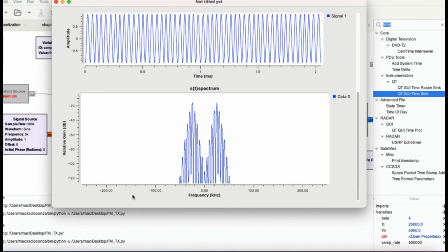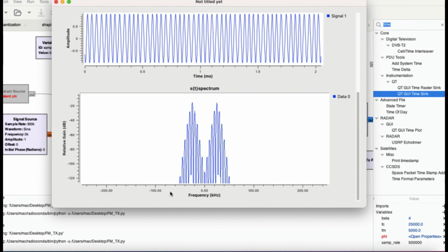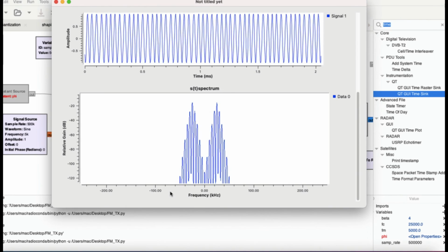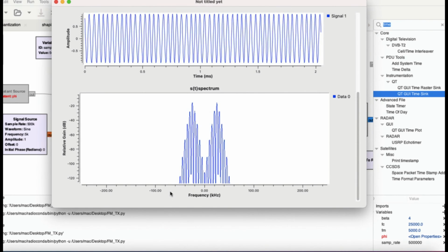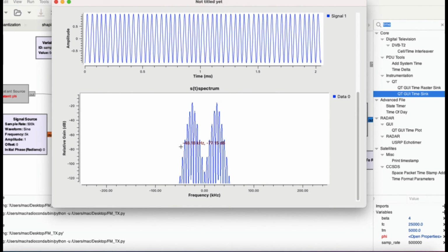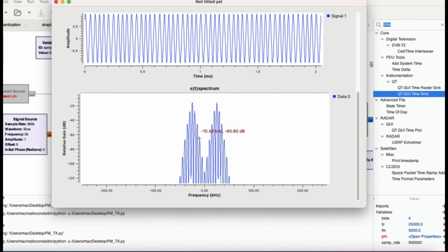You get these negative frequency components because of Euler's identity, because we're converting these complex signals. Otherwise, in a real life system, just like we did an example using our digital oscilloscope, you don't get to see any of this. These are just redundant values that you see due to the negative frequency concept using complex numbers.